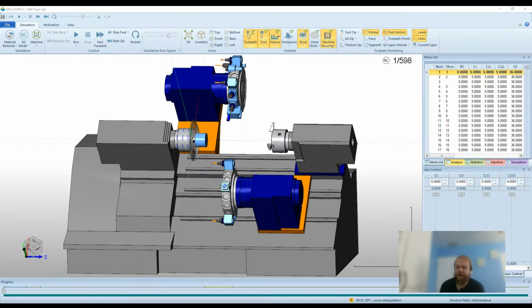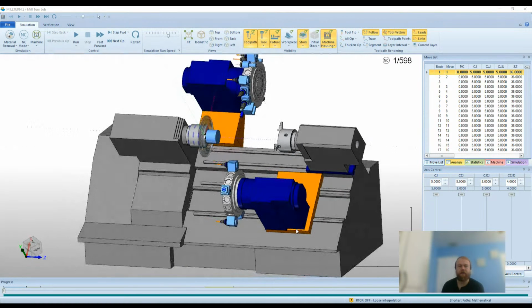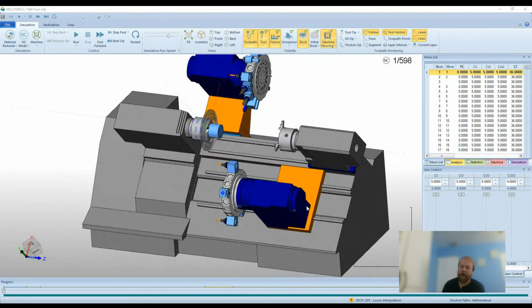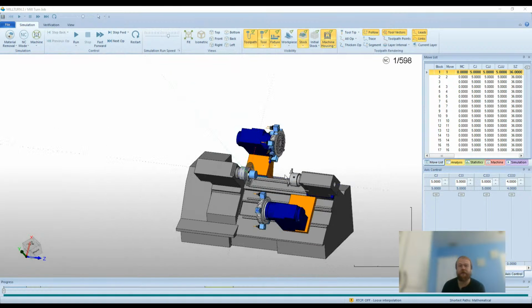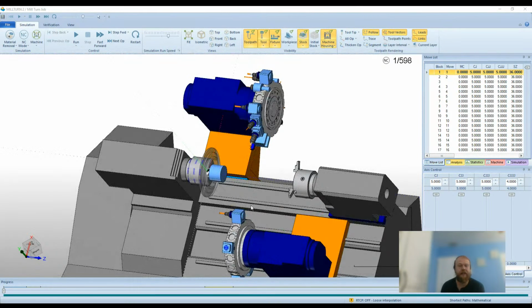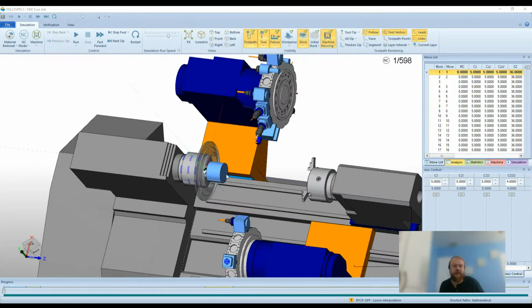Yeah, good point, Mark. Work offset XYZ. We could rename to work offset XYZ for simulation only. It's sort of implied there, but that's a good suggestion. It is in our help topics page. If you go to BobCAD-CAM help, it'll tell you all of the definitions there. But yeah, good thing to know is that it is in simulation only, and changing the work offset XYZ in machine setup, at the very bottom, it doesn't change anything in the G code there.